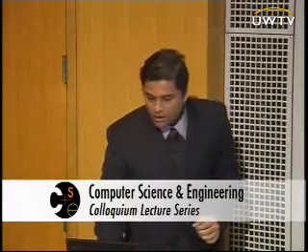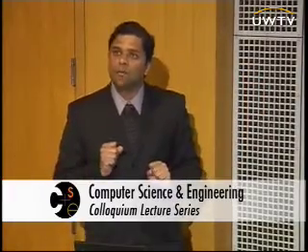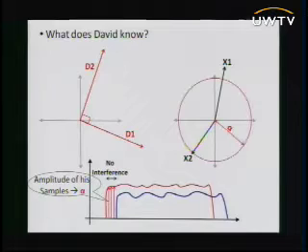But remember, he also has this interfered signal, which is interference free at the start and interference free at the end. So he can look at the complex numbers in this part, estimate their amplitude alpha, and he knows that his complex numbers have to lie on this red circle of radius alpha.